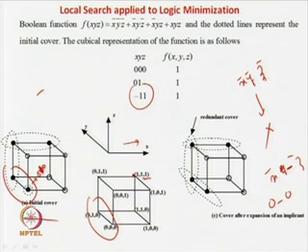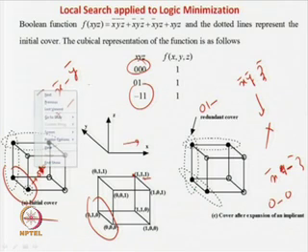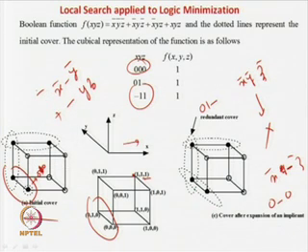Obviously, eliminating y prime from the first term makes it a valid solution, because it still covers the function and no new min terms are included. So it remains a valid solution, and then you can find out that the second term, 0 1 dash, becomes a redundant cover and can be removed. So your function will become x prime y prime plus the last term, dash y z. This will be your final function, because this middle term you can do away with.